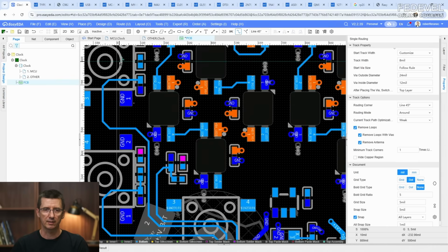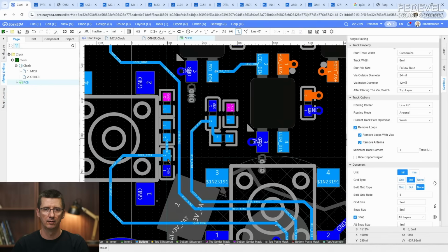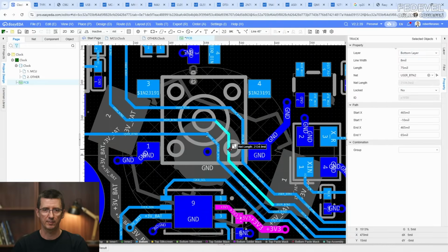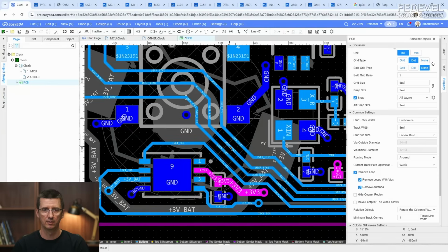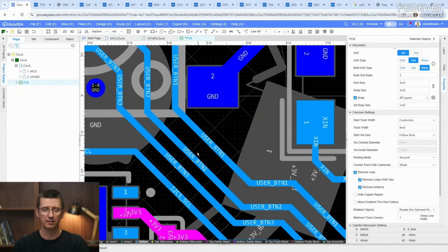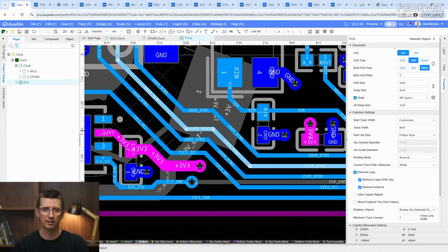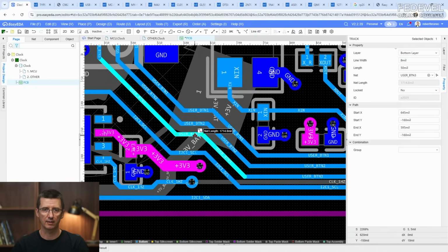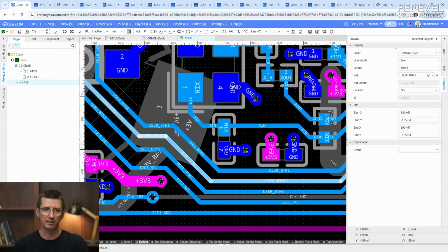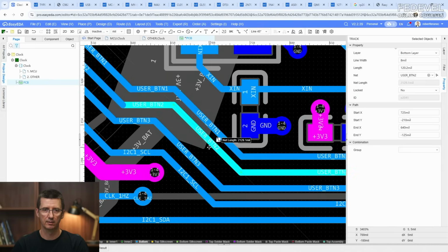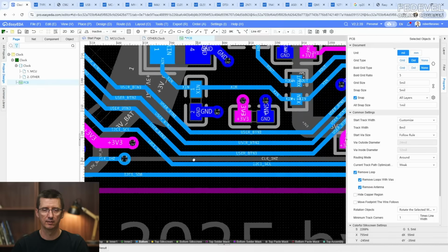Connect these resistors and capacitor. Keep space, okay, keep space. I'm making it nicer and spreading the tracks. So this is clock, okay? We would like to have it maybe a little bit further from the other tracks, especially if there is space. This is also a clock, so I'm going to move it a little bit away.